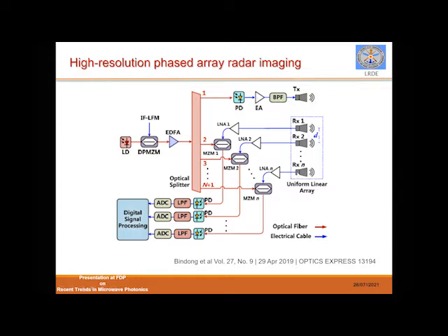When the signals are received, they are using photonic techniques to perform the down conversion of the actual echo signal. This MSDM along with the PD will be capable of doing the down conversion, and then it is given to the ADC for digitization, and further the signals are used here. But again, I will tell you, since I have put some effort in this domain also, there is a limitation here. Anyway, when I come to that part, I will explain.